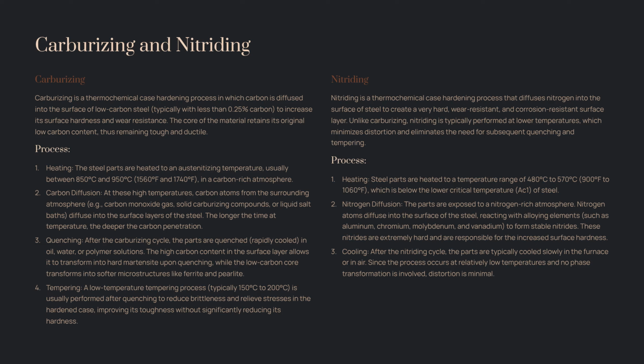Key characteristics. Purpose. Produce a hard, wear-resistant case by simultaneously introducing carbon and nitrogen. Mechanism. Diffusion of carbon and nitrogen from molten cyanide salt bath. Result. Hard surface, improved wear resistance and fatigue strength. Safety. Highly toxic process with significant environmental concerns. Replacement. Largely superseded by carbonitriding and nitriding.